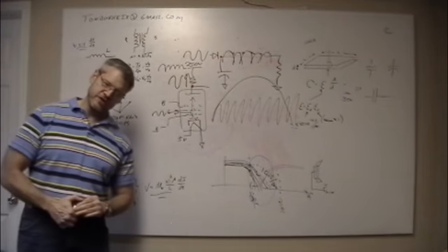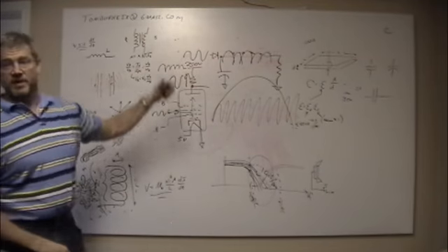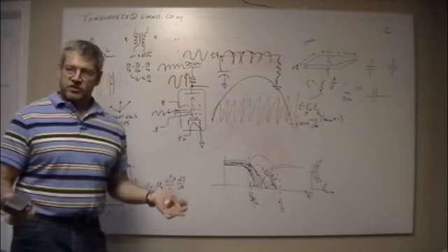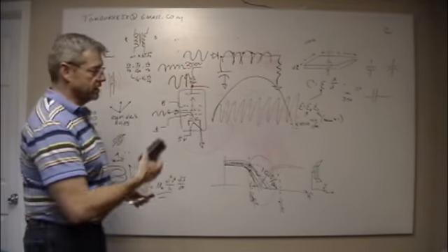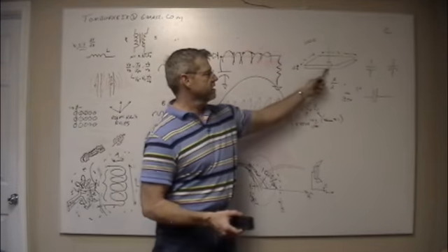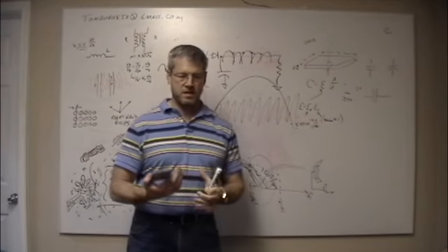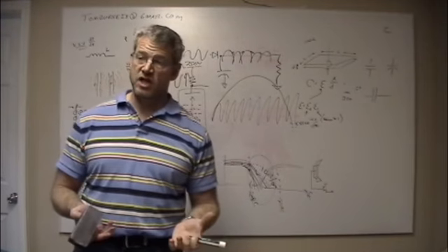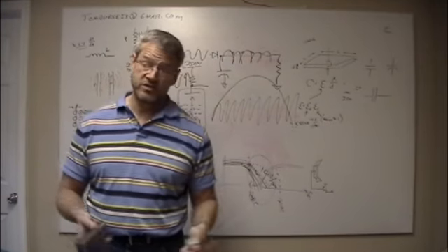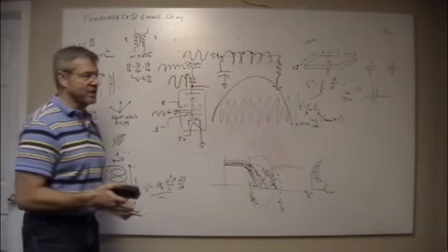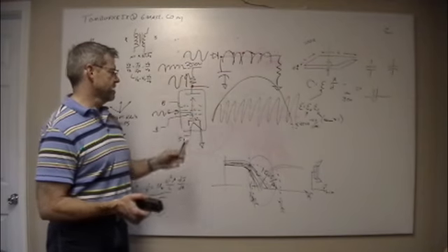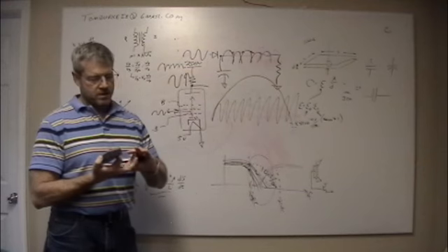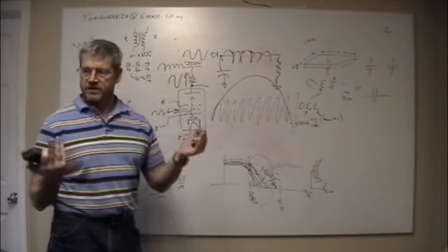That's one of those things, as soon as you hear that, it's like, oh yeah, it's over here in the power supply somewhere. And usually what happens, I'll use what's called an electrolytic cap. So electrolytic capacitor, it's not air in there, it's not mylar, it's an electrolyte that's liquid, and after time they dry out. That's what happens. Or sometimes the capacitors get old, if they're the old paper wrapped kind, they'll get little holes and little arcs in there and it just quits working.